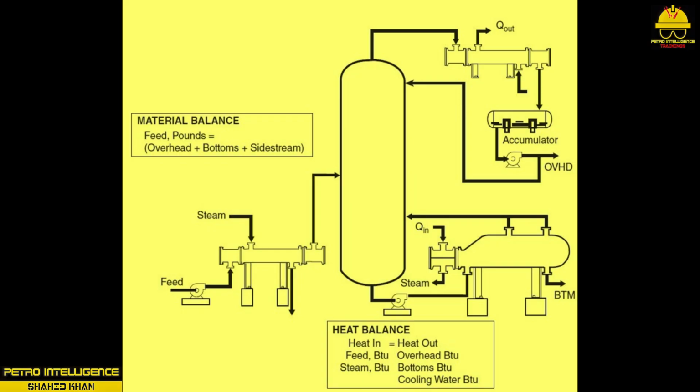Heat balance and material balance. Heat and material balance as shown in pictured variables must be understood by a technician to keep a distillation column functioning properly. As the feedstock is gradually heated up from 80 degrees Fahrenheit to operating temperatures, a variety of technical equipment can be used. For example, heat exchangers are frequently used to heat up materials. Typically, the exchangers are set up in series and the temperature is increased.